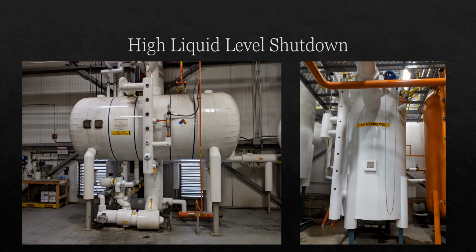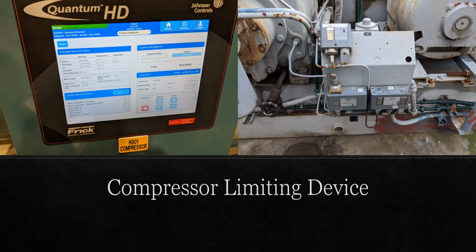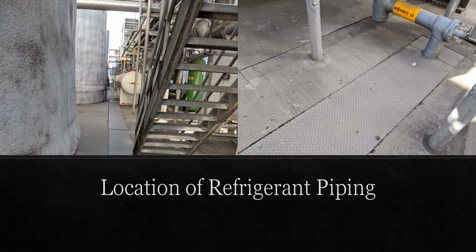Section 7.4.4 requires any vessel connected directly to a compressor suction line to be equipped with a high liquid level control to cause the compressor to shut down if high liquid level is detected in the vessel. Similarly, Section 7.4.5 requires compressors to be configured with a high discharge pressure limiting device, often called a high pressure cutout, to shut down the compressor when the safe range is exceeded.